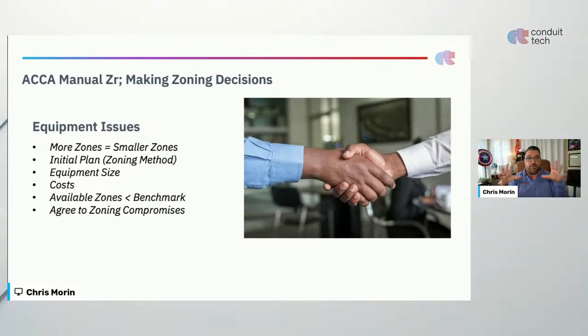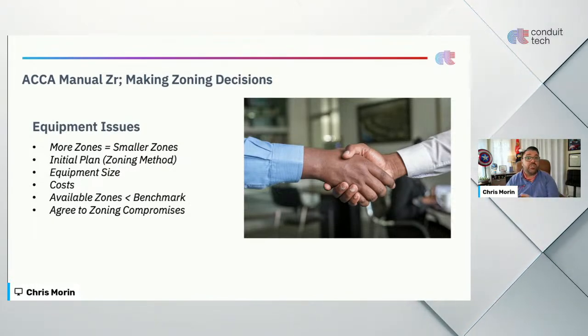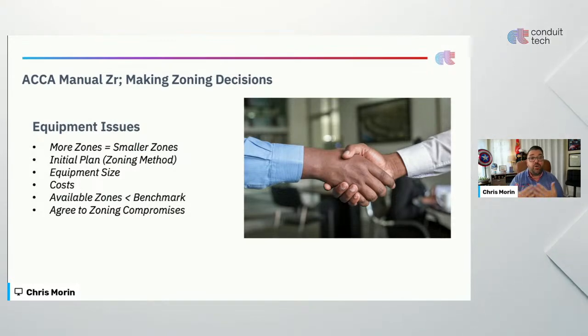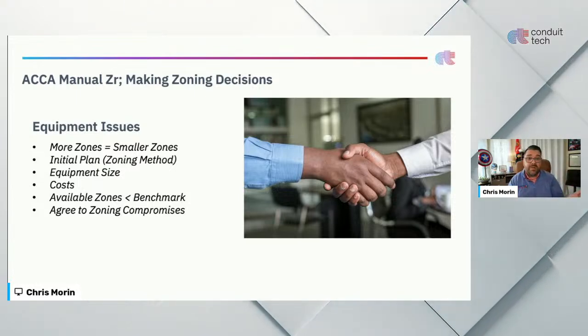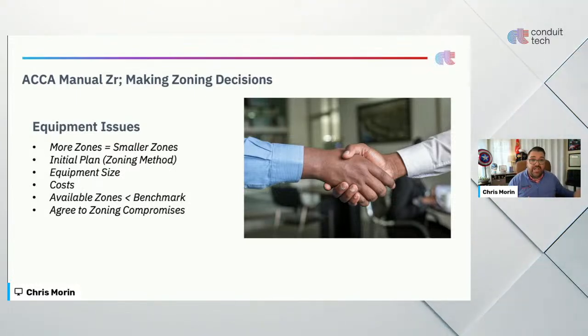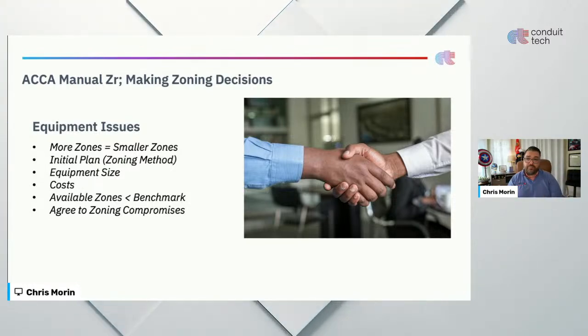The more you zone off one condenser or one furnace or one system, the less likely it's going to be able to perform under lighter loads, right? Because we're sizing the system typically for the 99 or 1% design temperatures. Here in New England, my design temperature is about 5 degrees. What happens when it's 40 degrees and we still need to heat the space? It's drastically oversized for that one zone if we continue to zone and slice that up, and it can't ramp down that far, right? So we have to consider the equipment capability.